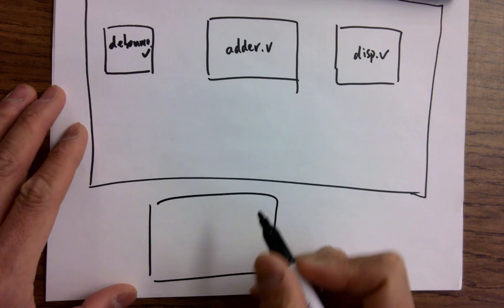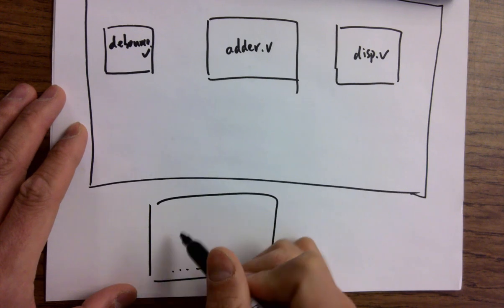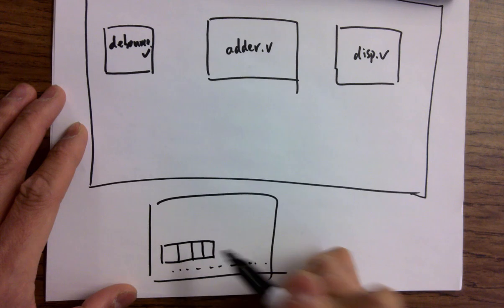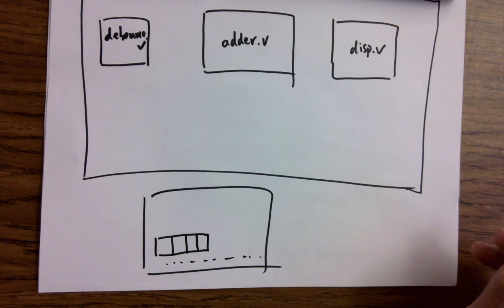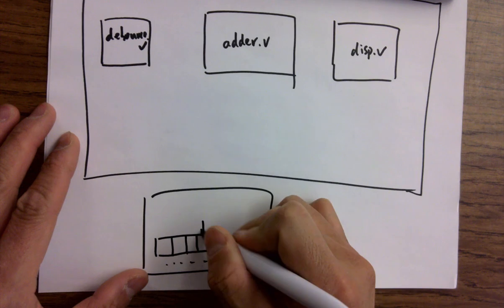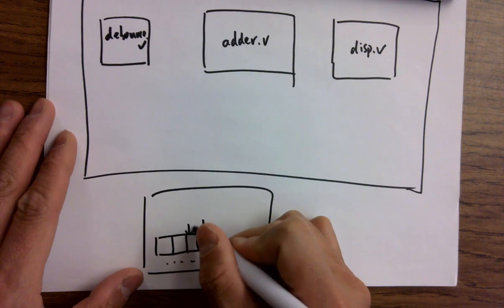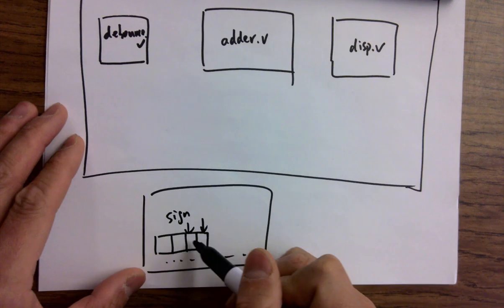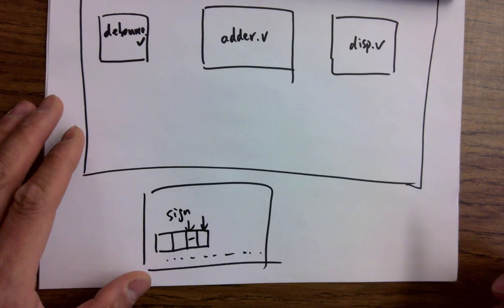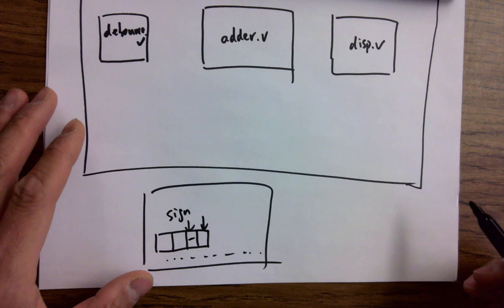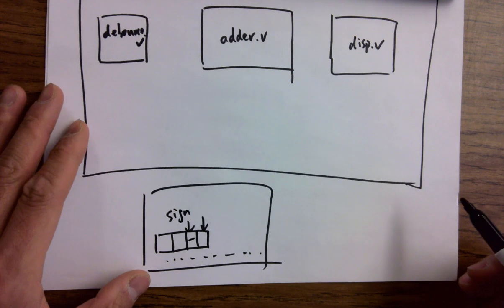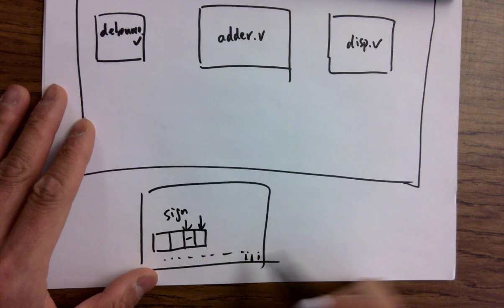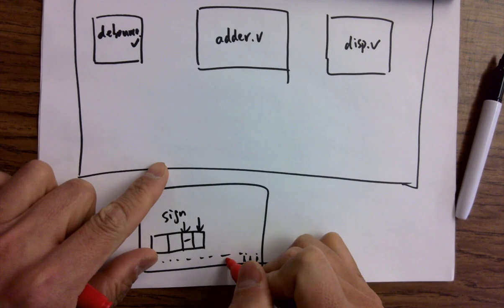So there's the FPGA, right? You got all the LEDs, and here's a 7-segment display. So it's just a one digit as a number. Another one is a sign. This is for sign. Okay, it's a sign bit. It's either nothing or a minus sign in front of it, depending on the 2's complement number. And it's a 3-bit number system. You have switches, 1, 2, 3, and 1, 2, 3.